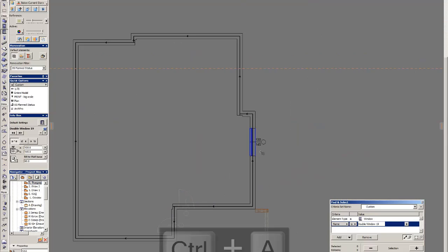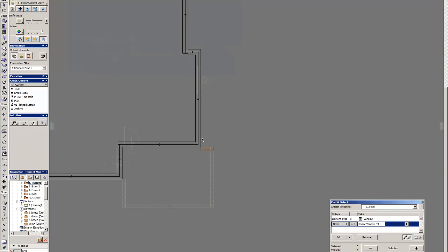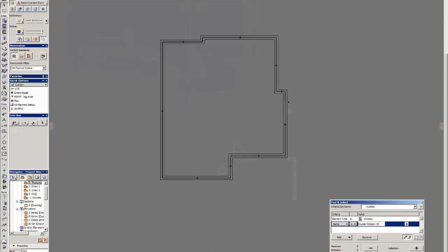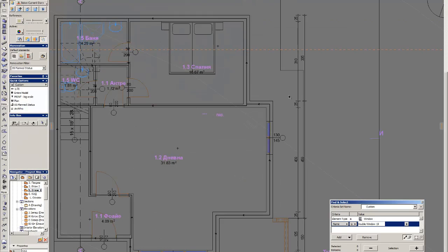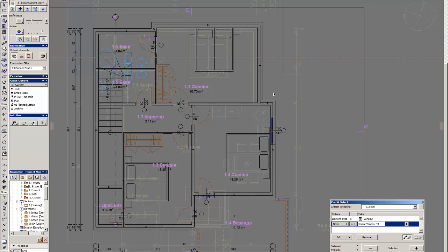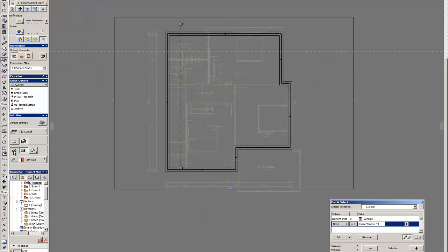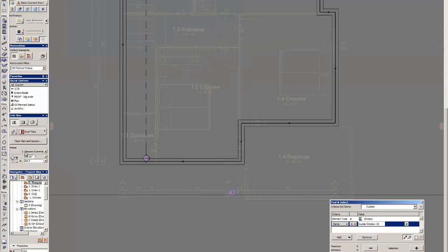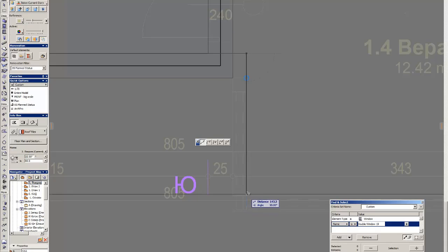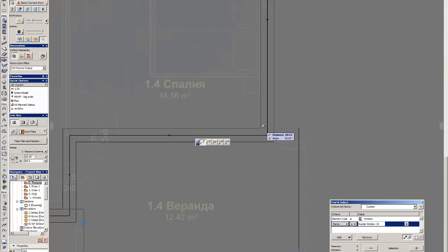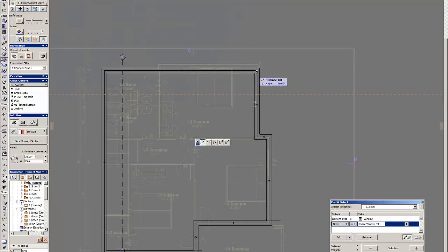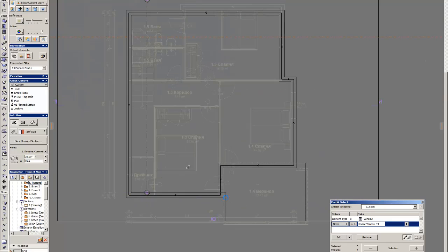We copy and paste all external walls, delete doors and windows, connect them correctly, let's simplify the geometry, and now we will create the roof using the polyroof tool. We draw the boundary of the roof, making sure that we cover also the balcony. That's the roof.